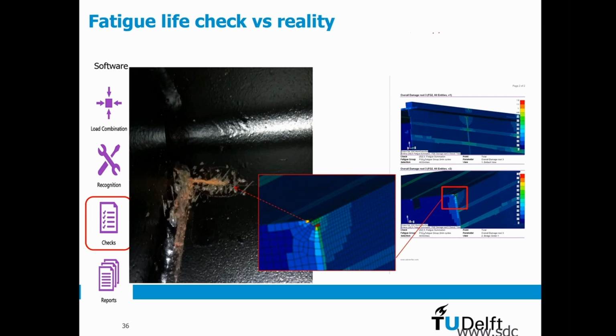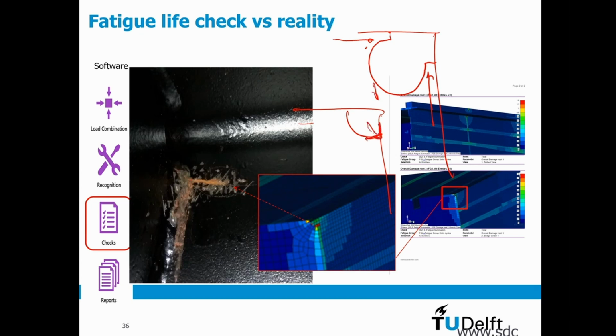So if you really want to avoid that stress concentration there, you need to weld something like this, and that's typically the best possible way to do that. So you have a smoothening here locally and a smoothening here locally, and if you just do this, basically if I have a stress in this direction, then this is a sudden change in stiffness, so that results in a huge stress concentration.